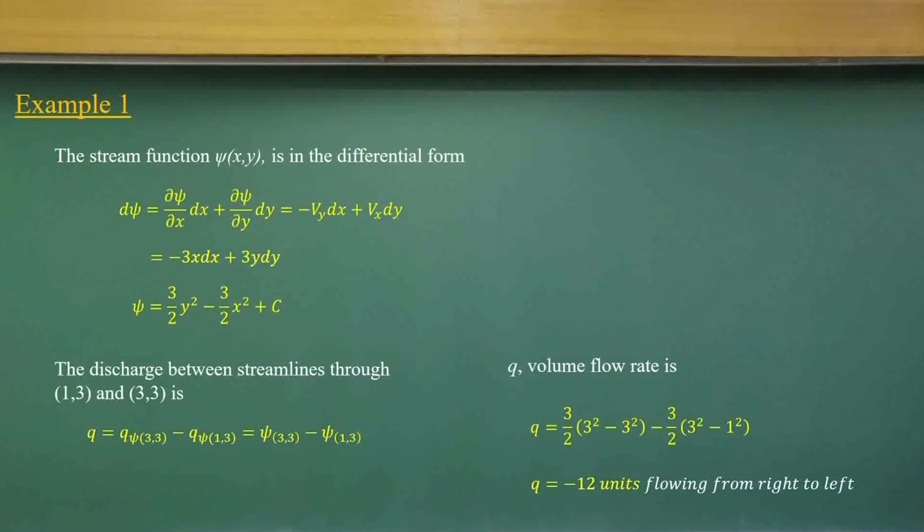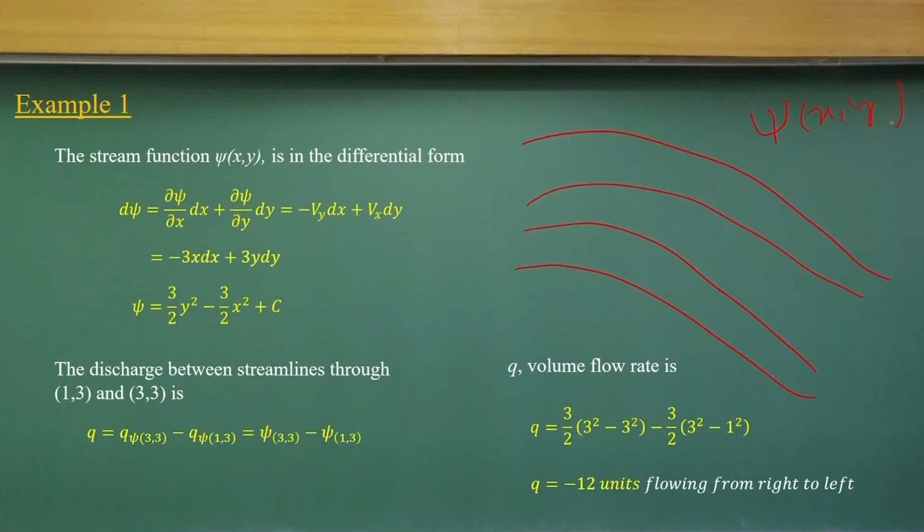Now, coming back to the stream functions, what we define. If you remember, these are my stream functions, which vary in x and y. I am talking about the steady streamlines in the x and y directions. As you know, the stream function changing in the x direction should be equal to minus Vy, and the stream function changing in the y direction should be equal to Vx.